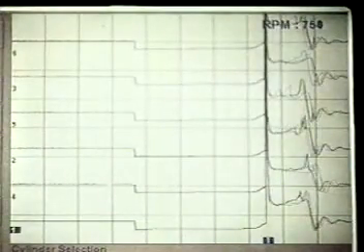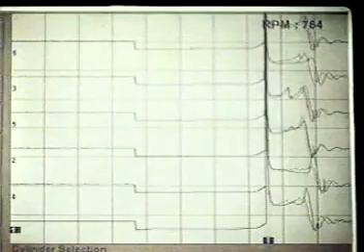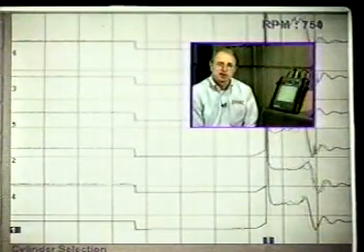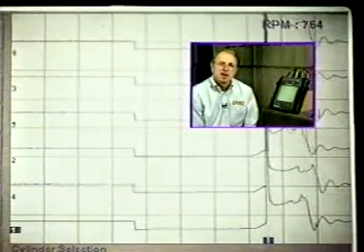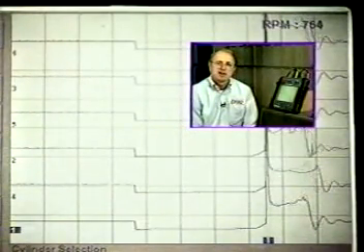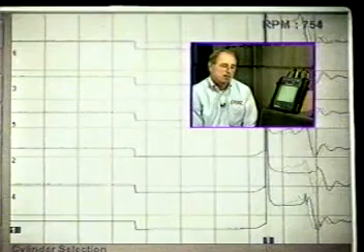So what we're going to do on this system before we make a diagnostic decision to tune the vehicle up, we want to go to the primary side of the circuit and focus on the dwell section to make certain that we do not have any dwell variation. Now, if you remember, we saw some relatively short spark duration periods in secondary, which alerts us to a problem. Before we make a diagnostic decision to tune this vehicle up, we want to go to the primary side of the circuit to make sure we do not have any dwell variation problem.